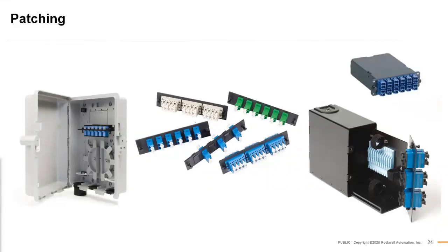And in some cases, what you'll see in these patch panels is you may have 6 fibers coming in, or 20 fibers, a multiple of 6 typically. But you'll see a bunch of fiber coming in, and you only use 2 or 3 of them locally, or 2 or 4 fibers locally, and all the rest of them are basically patched through or fusion spliced through, and don't ever actually come out of the box and onto a separate destination. And so you typically daisy chain your fiber from location to location, as compared to doing home runs and direct runs.